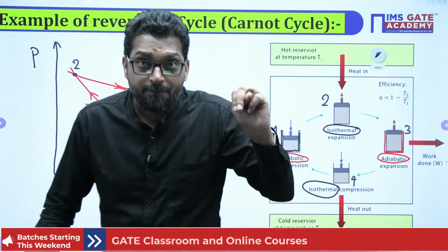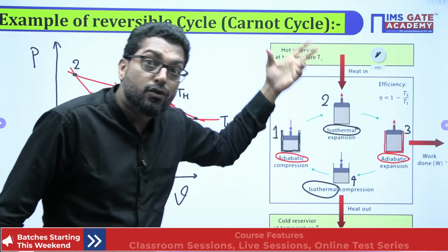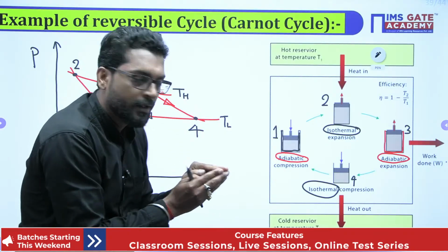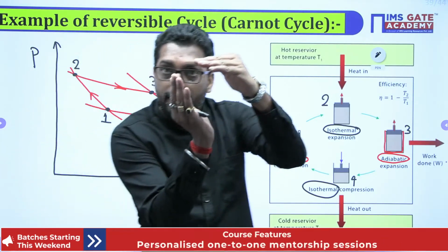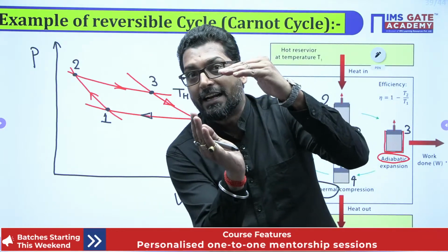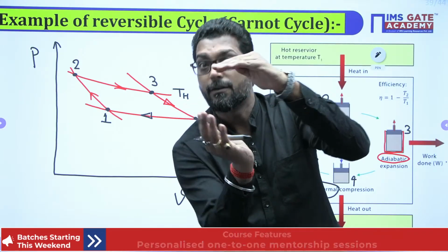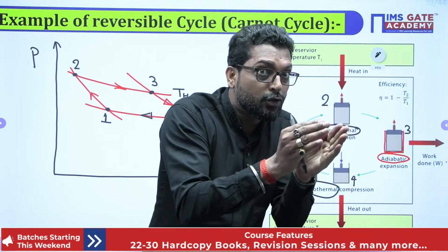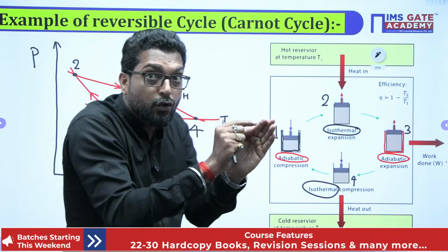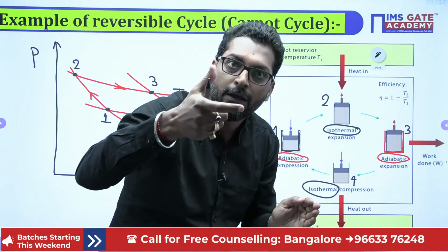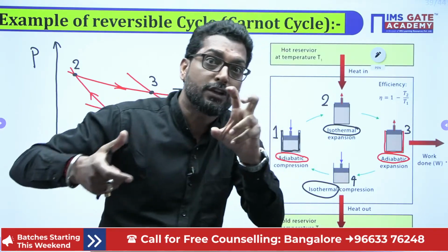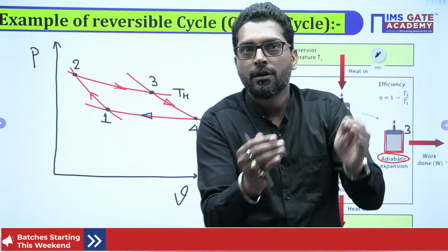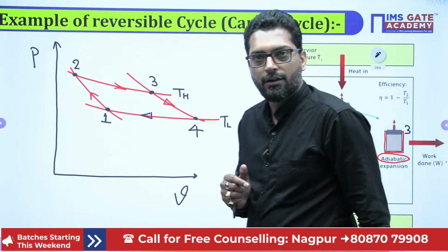The second answer is that, with the Carnot cycle, you can measure the extent of irreversibility also. If you design an actual cycle with the same temperature limits, you can compare its efficiency with the Carnot cycle. The actual cycle deviates from the Carnot cycle, so you can measure the extent of the deviation, and then improve that cycle to approach the Carnot cycle. Okay, these are the methods.